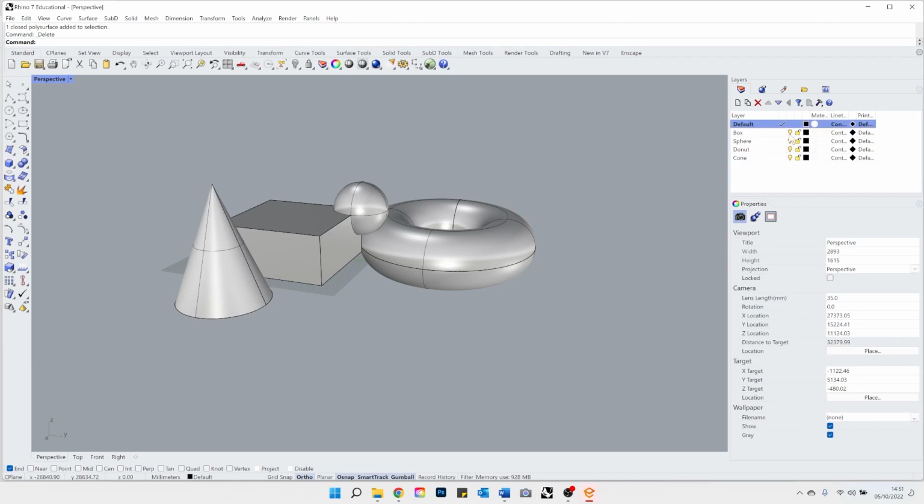There's also an option to make a layer invisible, the little light bulb. It's going to turn everything off that's currently on that layer. You can also lock the layer so you don't accidentally move it. For example, if you have a floor plan or a section that you're using as a reference and you don't want to accidentally move it when you create a wall or 3D object, you can lock the layer and you're not going to accidentally move it.